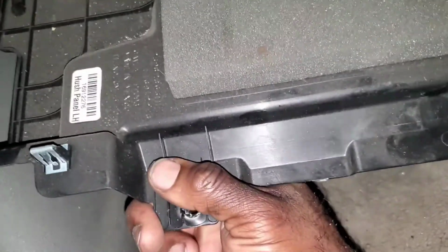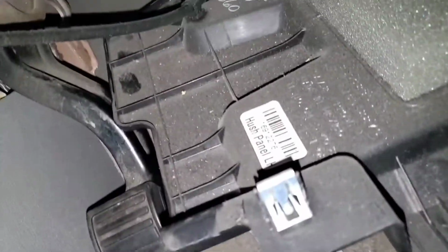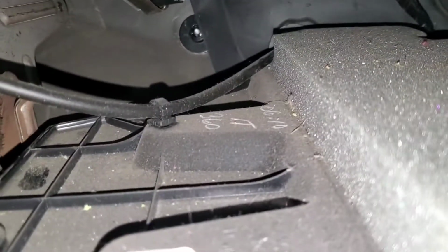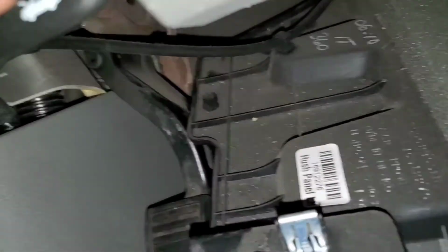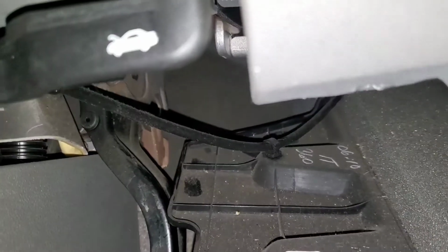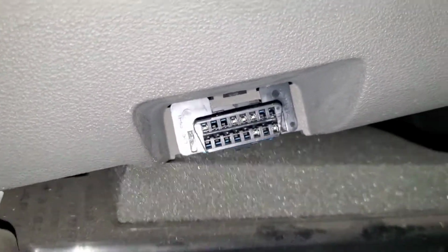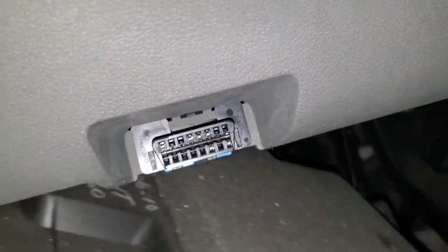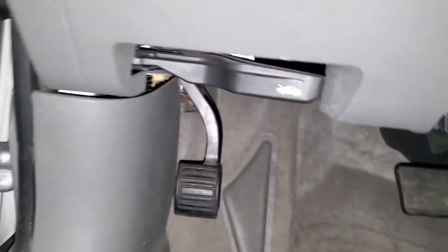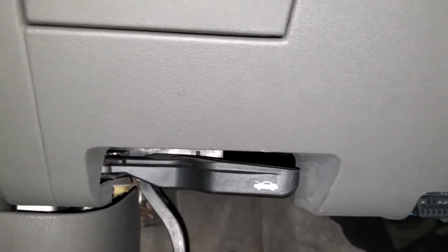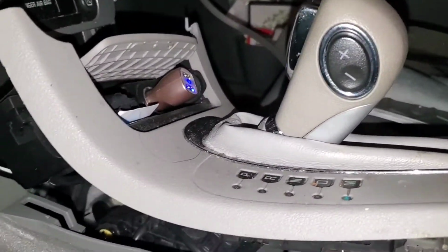What's holding it? Something's holding it. Gonna have to look under there. Feels like a harness clip. Yep, just like that. Will I need needle-nose pliers here? If I can just pinch and push. Yes, pinch and push. All right, so second trim piece. Actually, third, doesn't count. Fourth. All right, so we had 1, 2, 3, 4, and let's get this hidden bolt out of here.